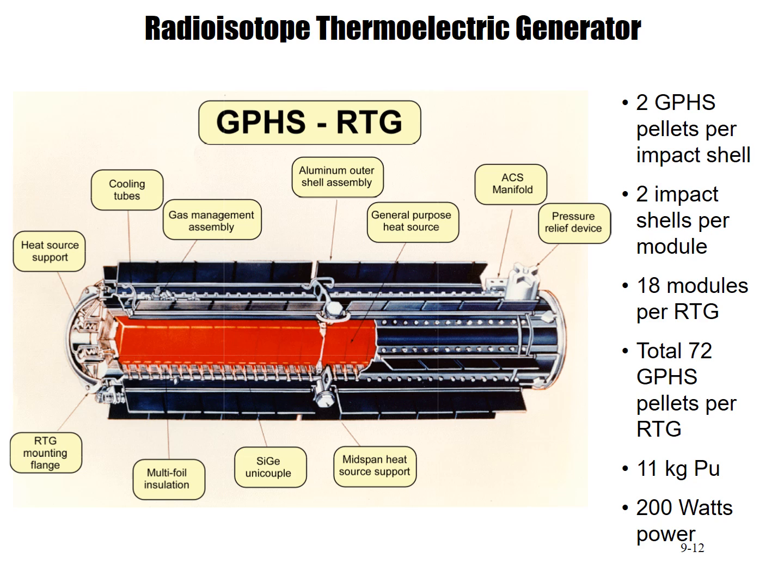Radioisotope thermal generators are also an application of these heat sources. As shown here, the heat sources are introduced into these generators. The heat is then converted to electricity. The overall yield is not very good, on the order of 20 to 30%, but this does provide a constant electrical source without any moving parts. So you basically have this thermoelectric generator which utilizes the heat coming from the radioactive decay of the plutonium-238.